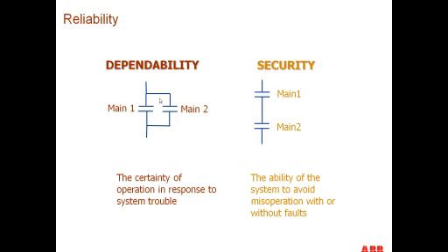Most times people use two sets of relays on high voltage systems to gain the dependability that they want. In some cases where they've got a very, very important system, like on a 500 kV system, some customers have used 3 relays all looking at the line and using a 2 out of 3 voting scheme, so 2 of those relays would have to see the fault before you would actually do the tripping. So there's several ways people have invoked this security and dependability over the years. And that's the question that came up.